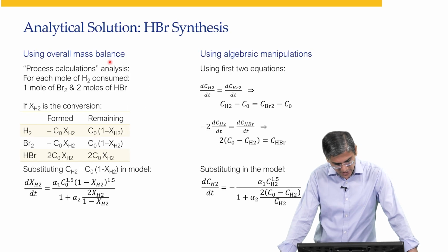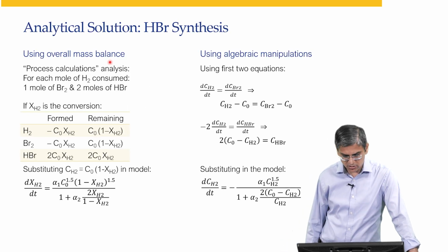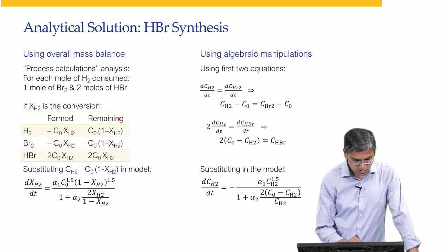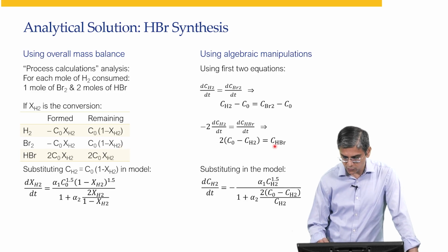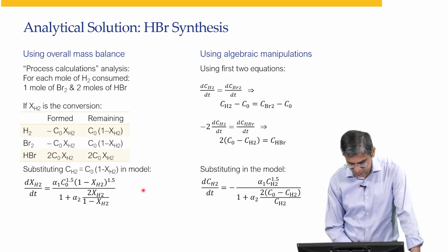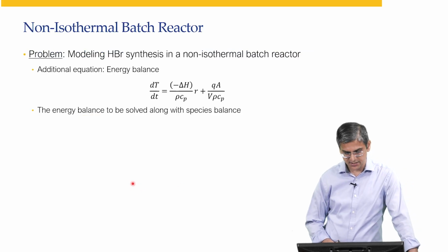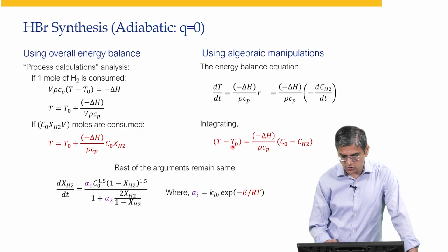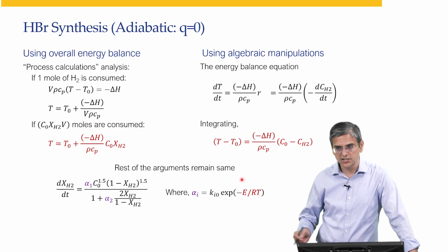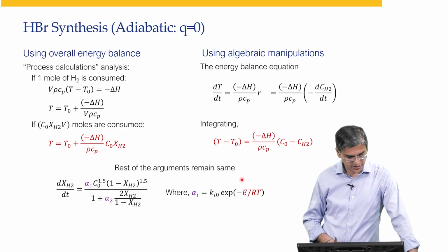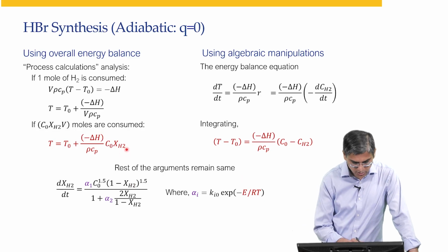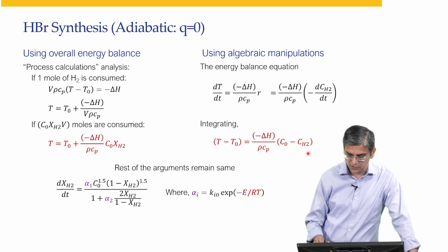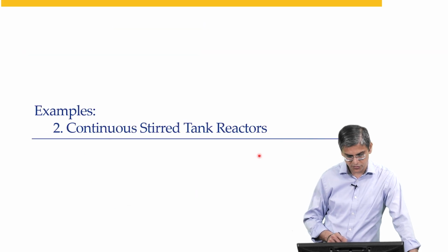Again, all of these things that I talked about, it's all there. If you are to use a conversion based approach or a concentration based approach, the result is exactly the same. If it was a non isothermal system, we will come to that again in the 8th module. You can simplify the overall equation irrespective of whether you use conversion based or concentration based approach.